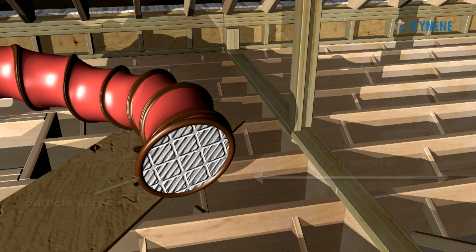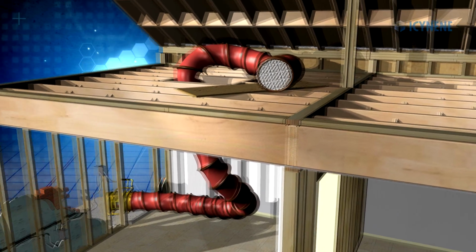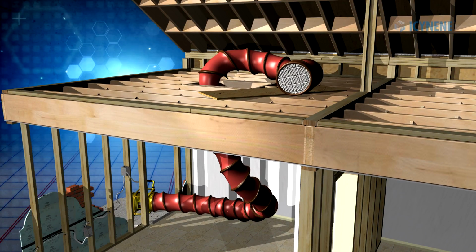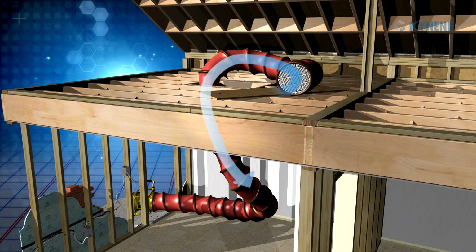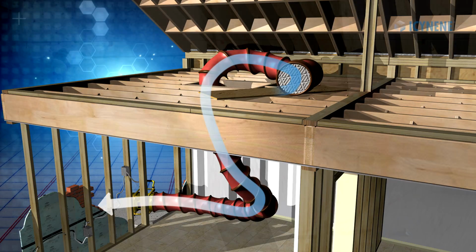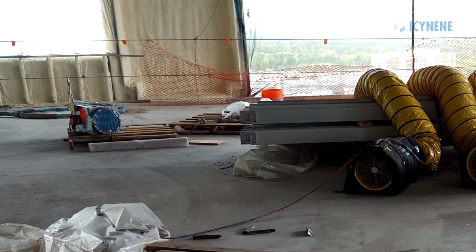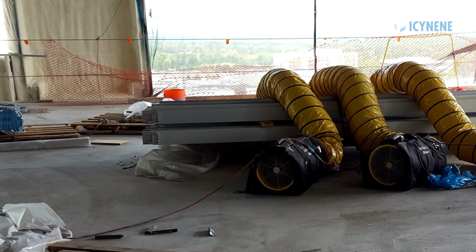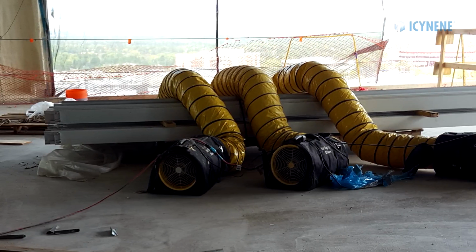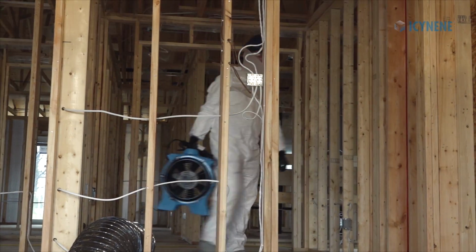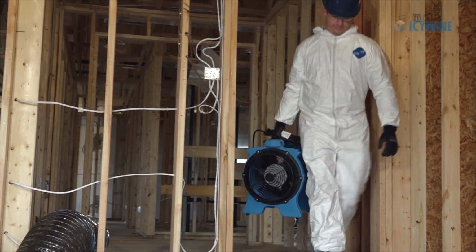Keep in mind that the fan's ventilation rate can diminish depending on the positioning of the flexible duct. The path of the exhaust air should be as efficient as possible with minimal curvature for maximum ventilation rate. Following these ventilation instructions while installing Icynene products will allow for a properly ventilated spray area, ensuring a safer environment for everyone.